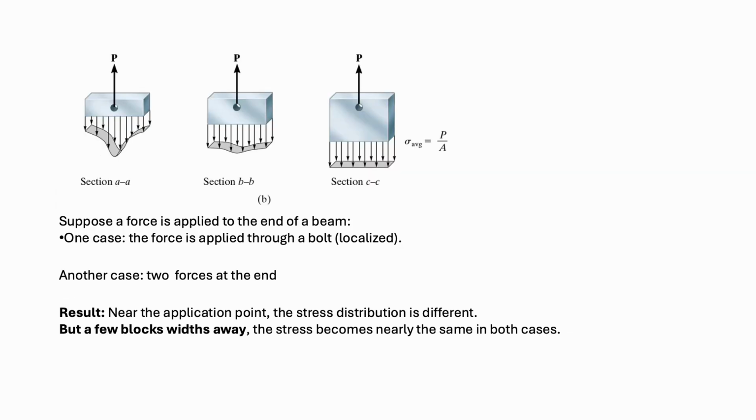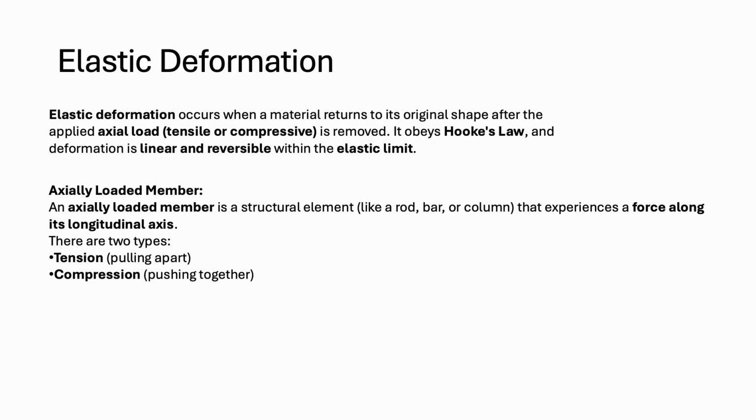If we have, for instance, a beam or column subjected to one force at the end, that is one case, and on the other hand we have a column which is subjected to two forces, the stress distribution will be different near the application point, but a few widths away, the stress becomes nearly the same in both cases.